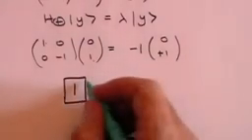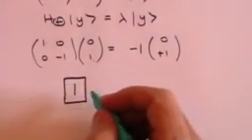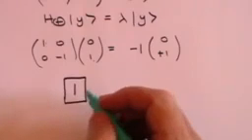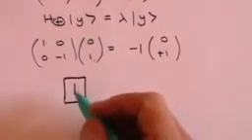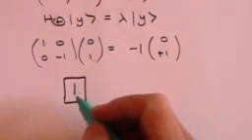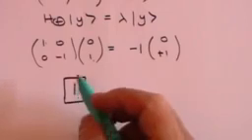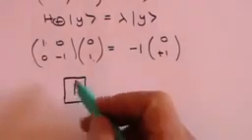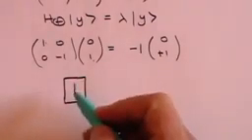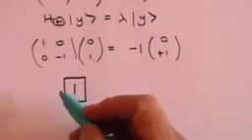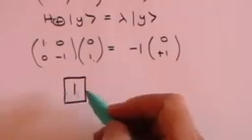And then if the light goes through it, and behind it you would have, say, a light-sensitive diode or some light-sensitive device. For the time being, the conditions are it can either be vertically polarized or horizontally polarized. If the light that hits this polarizer goes through, it must be vertically polarized. If it doesn't go through, it must be horizontally polarized.